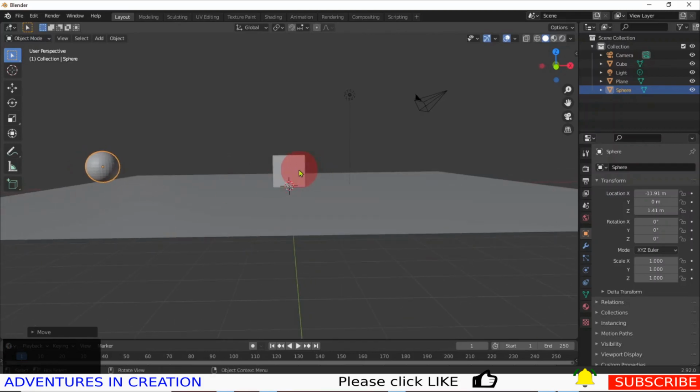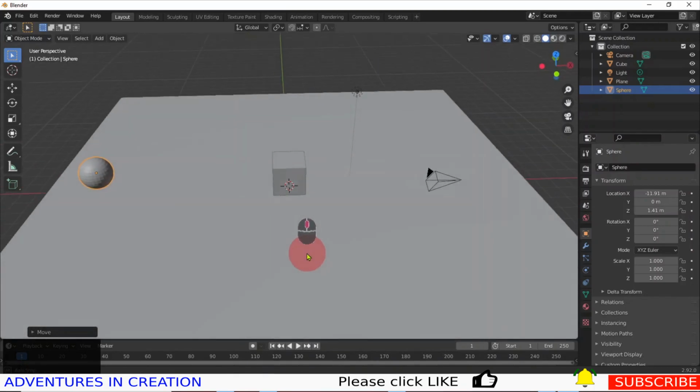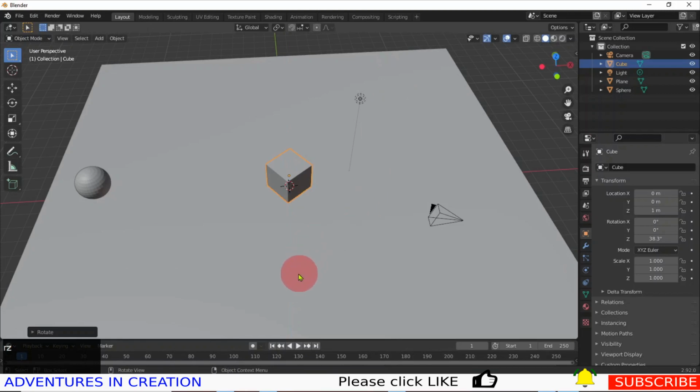And that cube is sitting there. We want a little bit of space behind it because we're going to knock the cube. And if we want to rotate that cube a little bit so it's not face on, we're going to click on the cube, R, and then Z because we just want to rotate around the Z axis. And we're just going to drag it around. So we'll put it there.